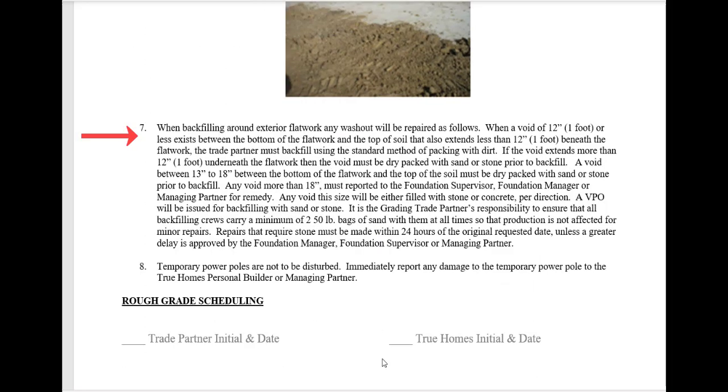When backfilling around exterior flat work, any washout will be repaired as follows. When a void of 12 inches or 1 foot or less exists between the bottom of the flat work and the top of the soil, then the trade partner would use a backfill standard method of packing it with dirt. If the void extends more than 1 foot, it must be dry packed with sand or stone prior to backfill. A void between 13 and 18 inches must use sand or stone, and any void more than 18 inches is reported to the foundation supervisor, foundation manager, or managing partner for remedy. A VPO will be issued for backfilling with sand or stone.